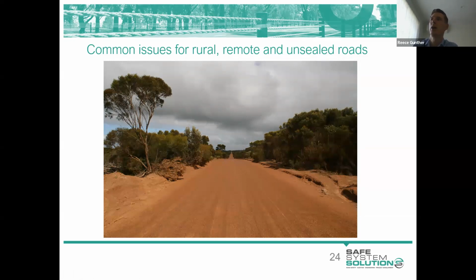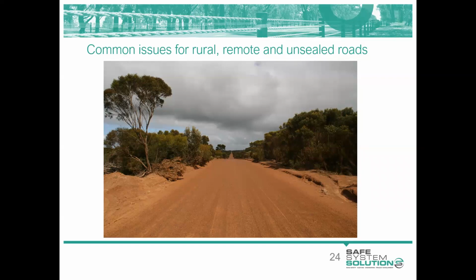That's a good one. So feeding off the back of that, coordination of the vertical and horizontal is important. Sometimes these roads are just constructed with a bulldozer and just pushed through the bush, and they just follow the existing terrain.